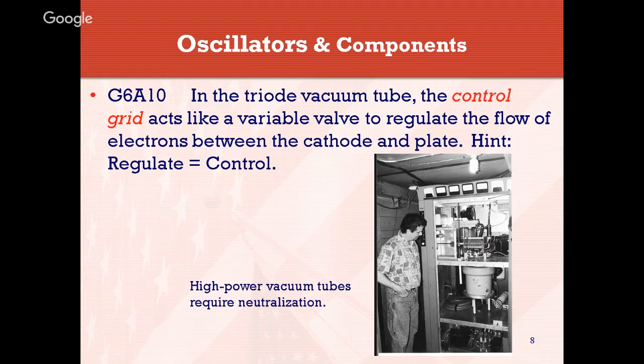Do we use tubes today? I'll tell you this, there's still lots of really good radios out there that are still quite usable, that are tube rigs. Most of the time, you'll find them as hybrid rigs, like the Kenwood TS520S, for instance. It uses a lot of electronic components on the front end of the radio, but in the final output, it uses tubes.